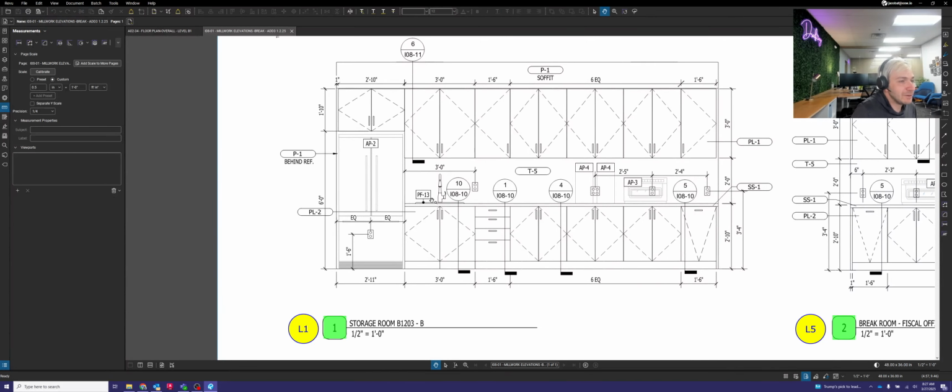Before we get too much further into this, we can already tell that we're going to be dealing with some upper cabinets. It looks like a trash pullout down here, a 2-door base cabinet or a few of those, and a 4-drawer base cabinet down here. And this looks like it's probably going to be an ADA base cabinet, meaning that the toe kick is going to open with the cabinet doors.